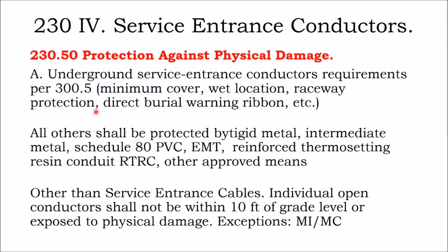All others shall be protected by rigid metal, intermediate metal, Schedule 80, EMT, reinforced conduit, something that's a little bit more robust. Other than service entrance cables, individual open conductors shall not be within 10 feet of grade level or exposed to physical damage, with the exceptions being more robust sheath wire.